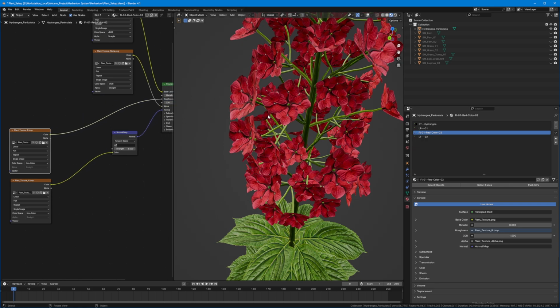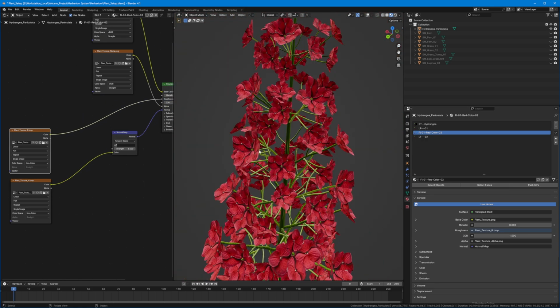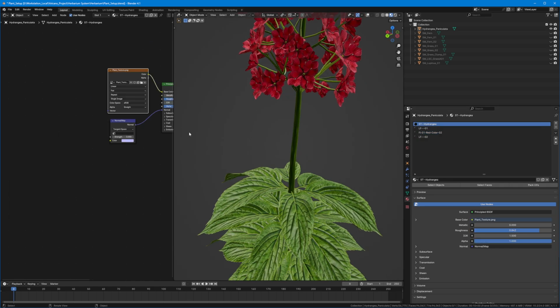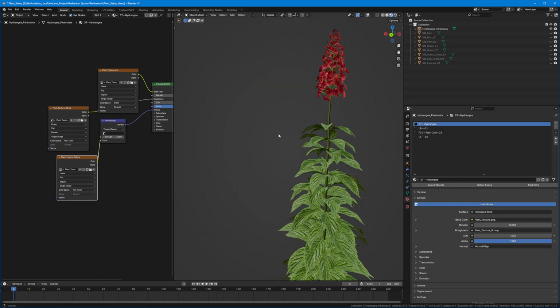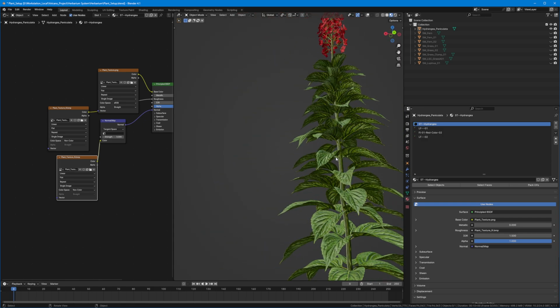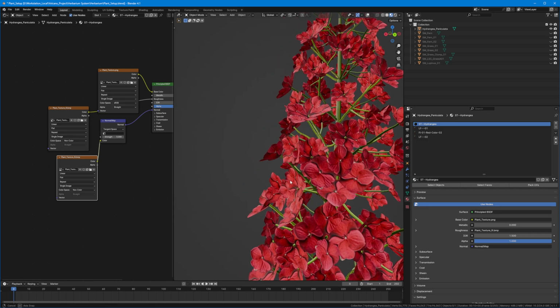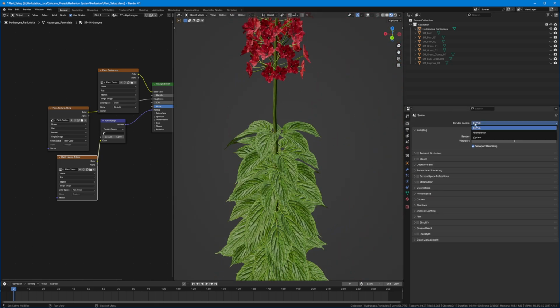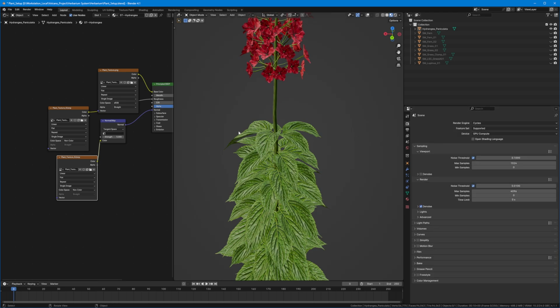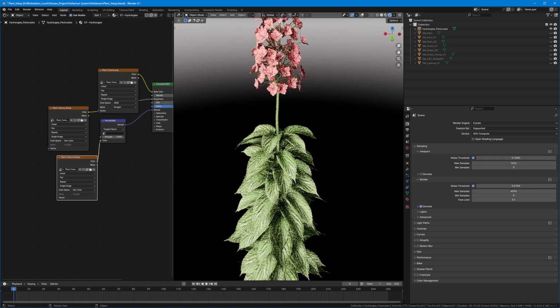And I'm going to put this over into the roughness. There wasn't much roughness to talk about when we generated this. And the final thing, we can do it here as well. So again, roughness, and then this one for normal and give it a value of 5. Okay, so this is how our plant looks now without any further adjustments. And this is in Blender, but we obviously want to bring this over into something else, like Unreal Engine, right? I can switch this over to Cycles as well if we would like to have a look.